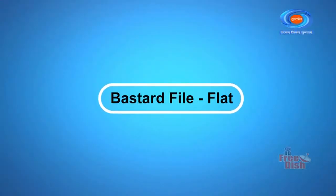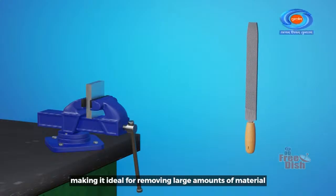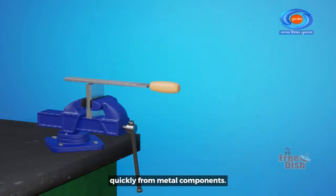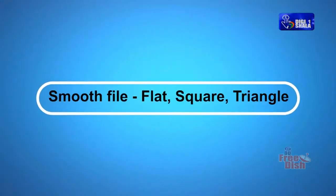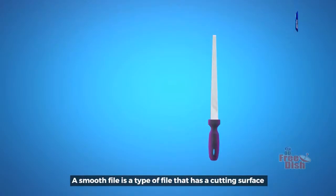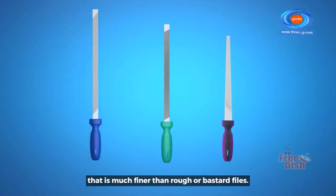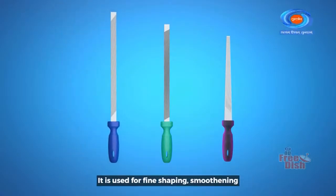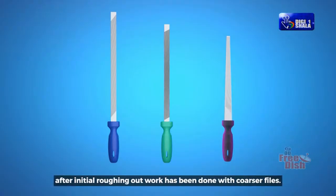Bastard file, flat. A bastard file is a type of file that has a coarse cutting surface, making it ideal for removing large amounts of material quickly from metal components. Smooth file, flat, square, triangle. A smooth file has a cutting surface that is much finer than rough or bastard files. It is used for fine shaping, smoothing, and finishing work on metal components after initial roughing out work has been done with coarser files.